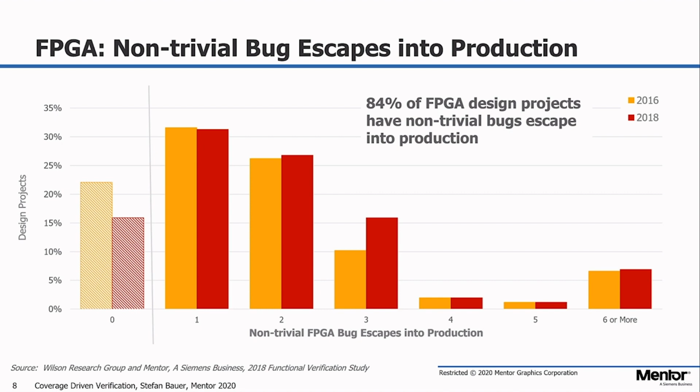For example, a project has adopted functional coverage, yet the fidelity of their functional coverage model might be poor due to their inexperience. To avoid that you become one of the 84% with non-trivial bug escape, I will go now into the details of code and functional coverage, simply to improve a little bit your experience with these techniques. So let's talk quickly about code coverage and the different types of it.